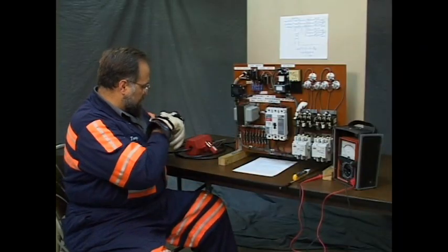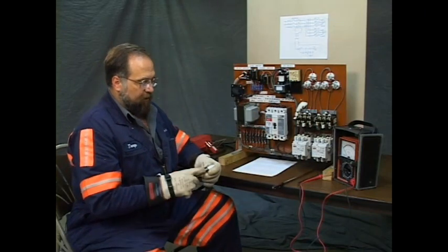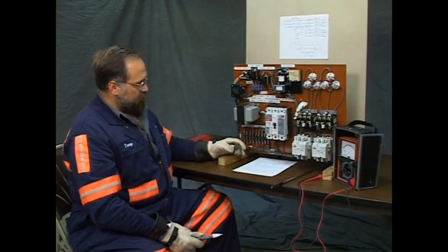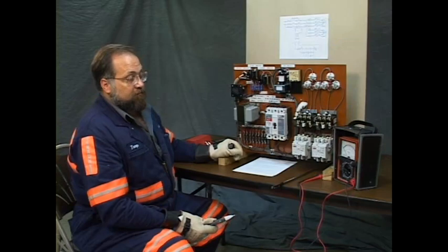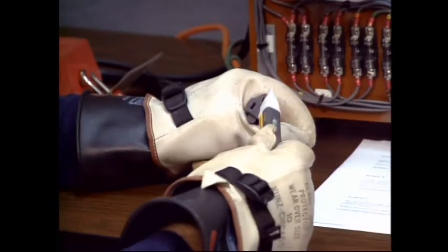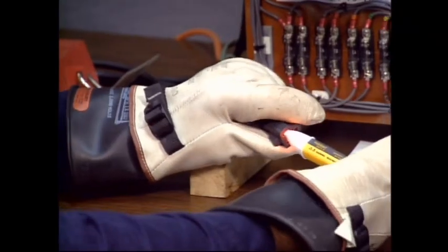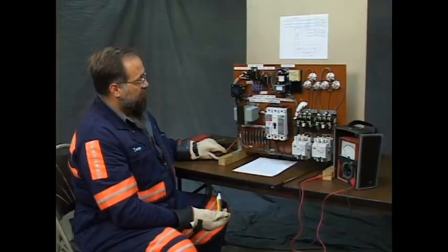We'll stow this key. Now let's check it and make sure the power's off. When dealing with electricity, you can never be too sure because these are often one-time mistakes, all you have. So let's test on a known live circuit. The purpose of this test is to test the instrument, to make sure the instrument's actually working. And it is.